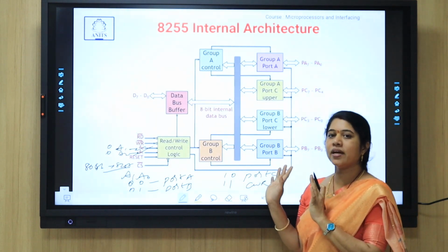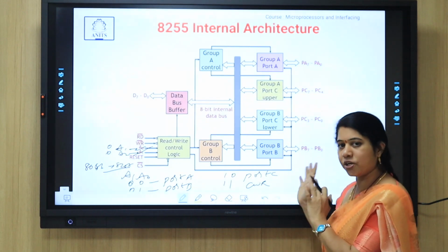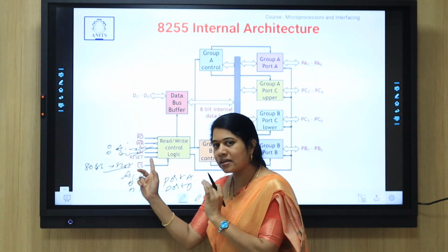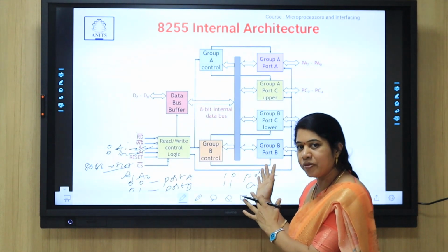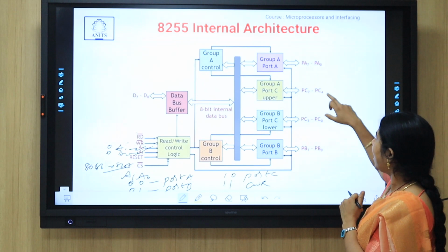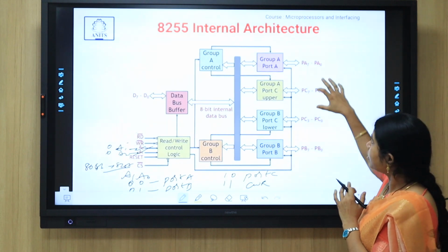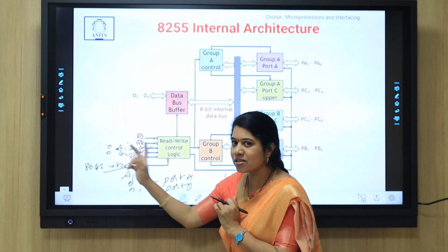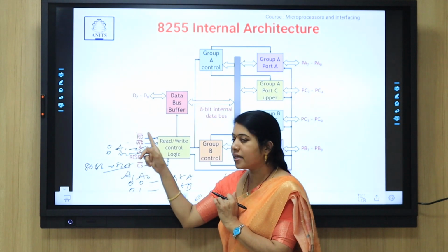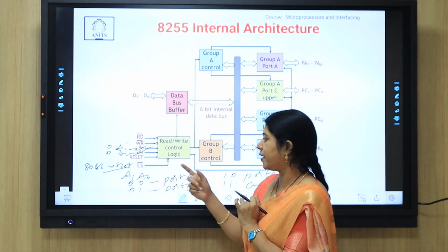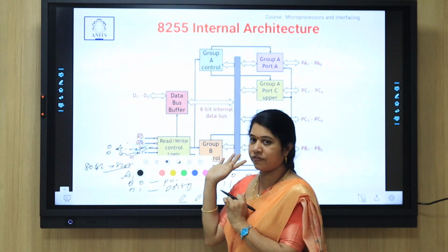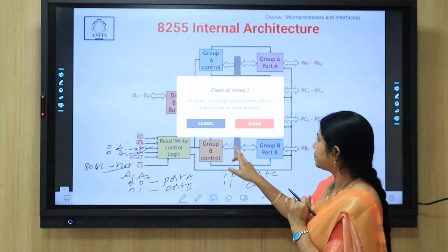So we are talking about the 8086 interfacing with 8255. So I am explaining what are the address lines that are connected to this 8255 in order to select the ports. Yes, there are three ports, port A, port B and port C. Okay. In order to select these ports, processor has to send address on these lines A0 and A1. Here, when 8086 is interfacing with 8255, A1 and A2 address lines are connected with A1 and A0 lines of this 8255. When these two are 0, 0,